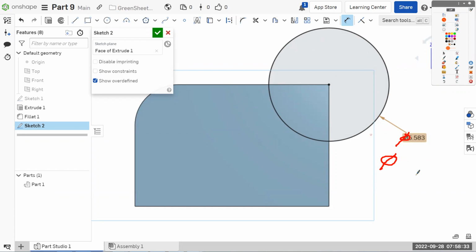So the dimension, you're saying whatever number you put in here is the distance all the way across the circle. Okay, for an arc, the dimension is its radius. So our 3-point arc would be, if we were doing it like that, you can see its dimension is r, meaning that if we put a dimension on this, you can see it's dimensioning to the center point, not all the way across, like the way that this one is dimensioning all the way across.